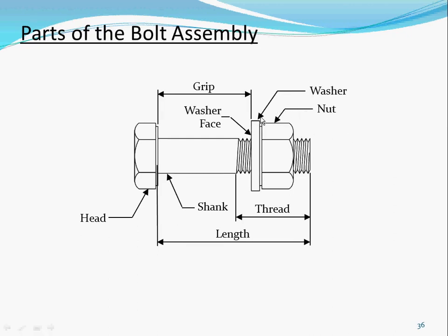The washers are typically required when you're pre-tensioning any kind of connection. Because of the area of the head, you might be digging into the steel a little bit, so they're trying to spread out the load. That's why the washers are there, so you don't dig into the soft material over a smaller area. That's why there's a chapter in the RCSC: when do you use washers, and what type of washers do you use?